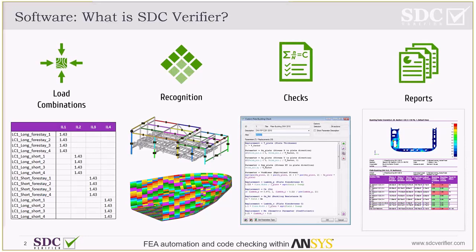SDC Verifier is a post-processing tool built on top of Ansys, which helps you make the load combinations and recognize structural members, because checks are done on structural members and not on the finite elements. Then we have the checks themselves according to many popular industry standards, and automatic template-based reporting, which helps you generate the complete document within a few clicks.